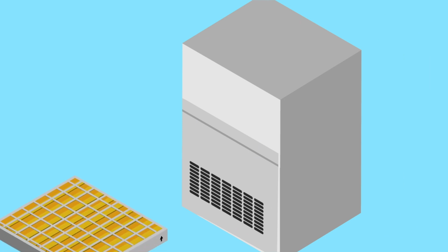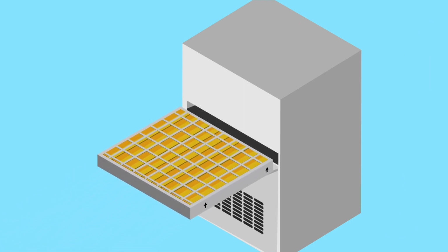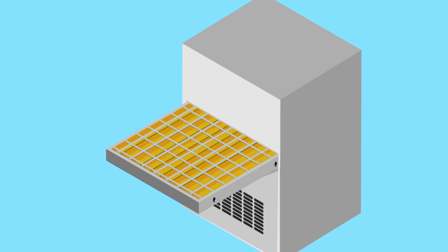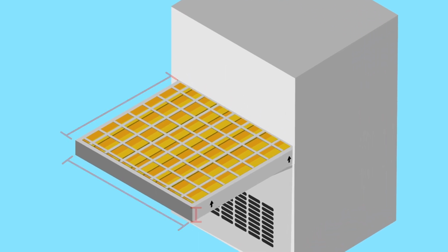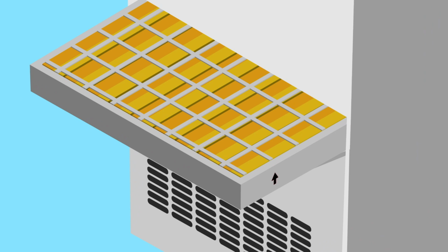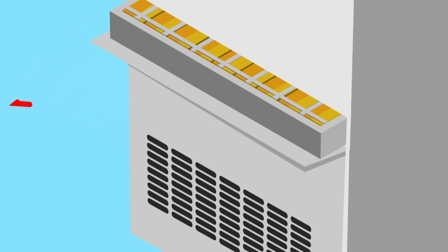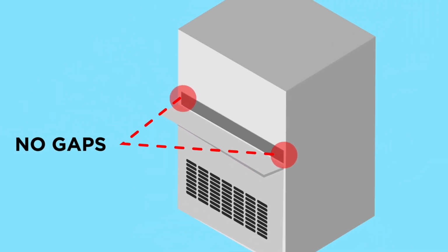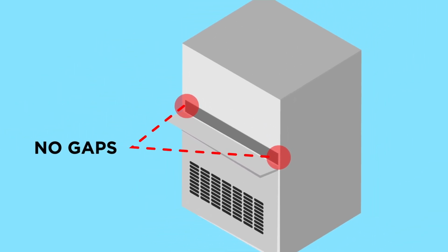Filters inside of HVAC systems are inserted into a slot or frame that holds the filter. It is important to ensure that the filters are the correct size, including length, width, and depth. The side of the filter will have arrows indicating the correct direction of airflow through the filter. They must be installed correctly so there are no gaps that allow the air to bypass the filter.